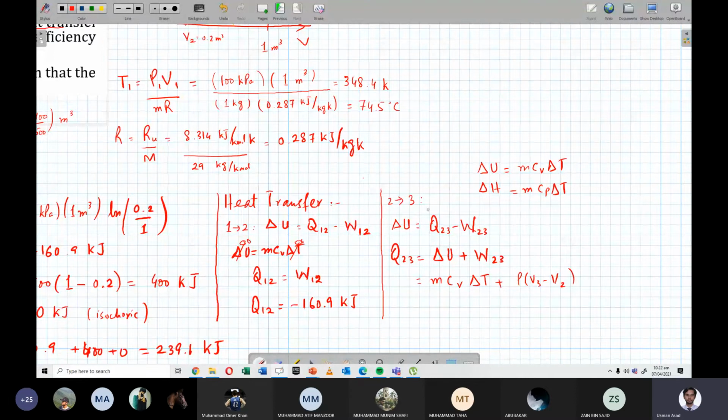What you are saying, that the process is a constant pressure process, you are absolutely right that you can just say the heat added during this process is overall equal to mCp delta T. But this is not wrong either. This is stating that the first law states that delta U is equal to Q minus W, which means Q is going to be equal to delta U plus W. The thing is, both of these are going to give you the same answers, and if they don't, we're doing something wrong. And you can actually check that on your own time as well.